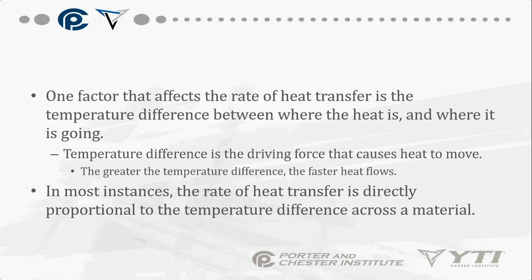Okay, one factor that affects the rate of heat transfer is the temperature difference between where the heat is and where the heat is going. Temperature difference is the driving force that causes heat to move. The greater the temperature difference, the faster the heat is going to flow. In most instances, the rate of heat transfer is directly proportional to the temperature difference across any given material.